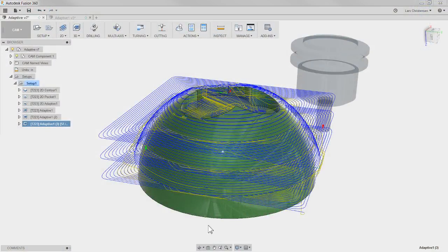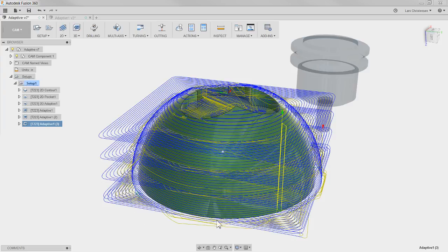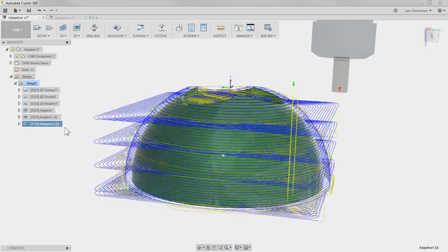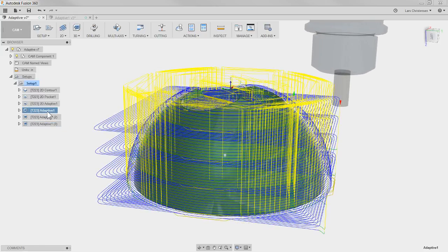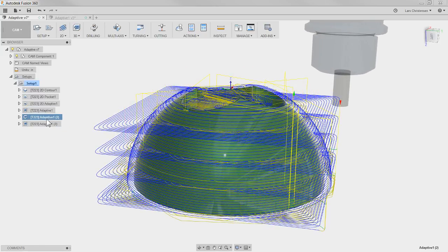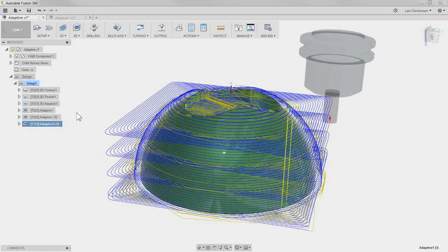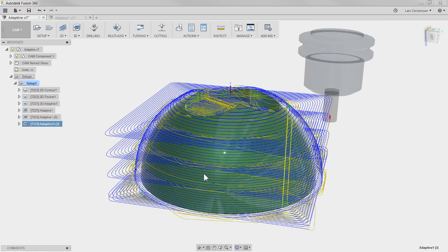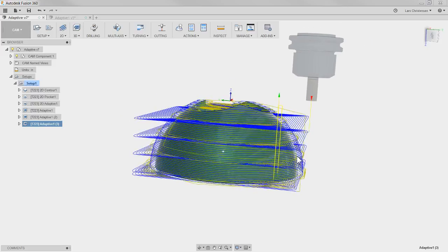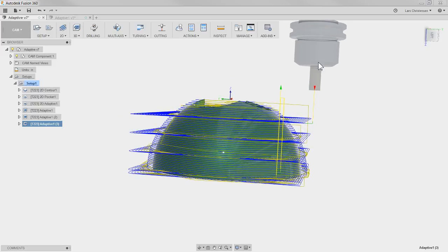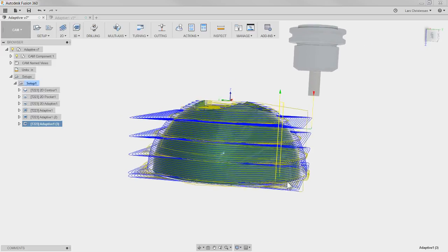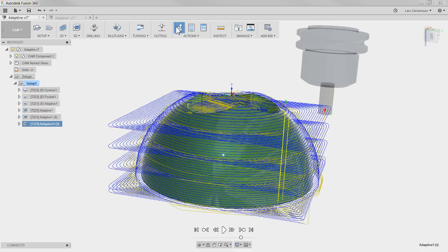The last thing I want to show you in here with this toolpath, still calculating, that you might like is, now we can look at rapid. First one, second one, third one. There's a couple of rapid moves that were eliminated. But one of the things that you probably would have considered right now is, wait a minute, if you're machining with that little end mill all the way down to here, aren't we going to get some collisions?